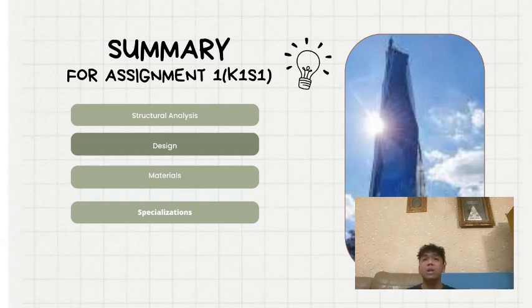After that, Menara Merdeka 118 has some special structural elements, which are outriggers and belt structures to reduce the excessive drift due to the lateral load, as well as a slender and flexible spire for the broadcast antenna and height element. Other than that, hammerhead walls to increase the strength of the building, and a raft foundation and fin wall.